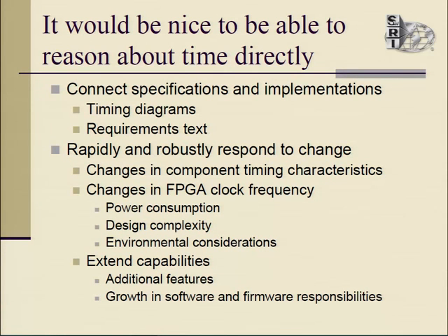And maybe even more importantly, we'd like to have a better mechanism to very rapidly and robustly respond to these kinds of changes. Maybe there are changes in the component timing characteristics. Maybe we need to change the FPGA clock frequency because we need to lower the clock rate to reduce power consumption. Or our design has become so complex we can no longer close timing at the rate we'd hoped to. Or environmental considerations require us to lower the clock rate.